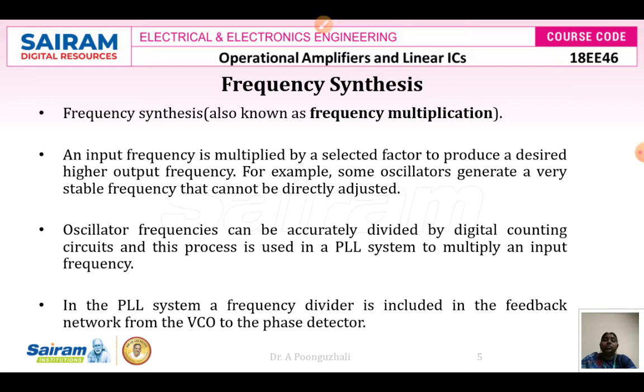Next we are going to see frequency synthesis. The other name for frequency synthesis is frequency multiplication. In the basic PLL block diagram, the output from the oscillator is given to a frequency divider network. The output of this frequency divider is given as input to the phase detector.